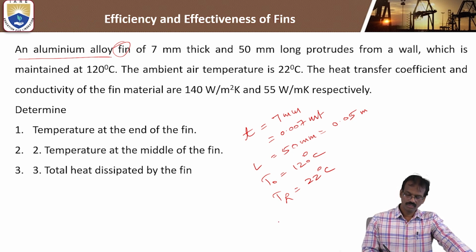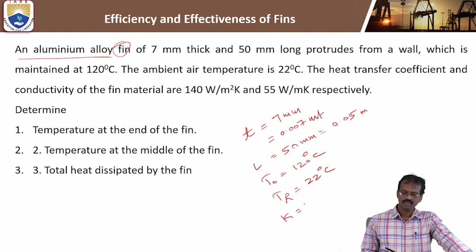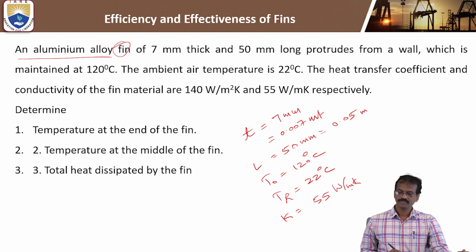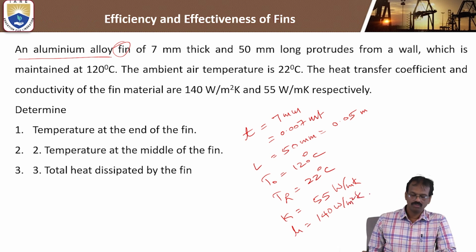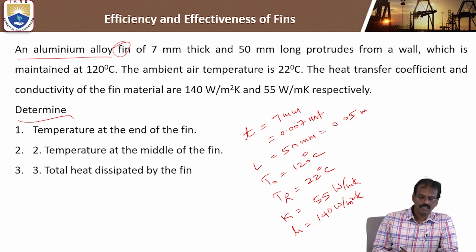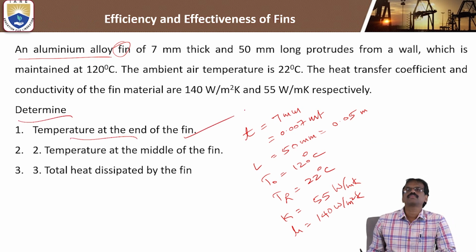So both are given. Thermal conductivity k is equal to 55 watt per meter Kelvin, and heat transfer coefficient h is equal to 140 watt per meter square Kelvin. So these values have been given. Okay. Determine first the temperature at the end of the fin.